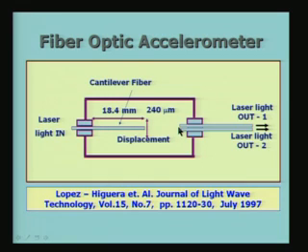At the downward side, I have got two optical fibers to collect the light which is coming from the left. These two fibers are kept with a small difference of spatially different positions, and you can see these are the two. So, what will happen is, if the laser beam is coming through this, a part of the laser light will enter through the 1 and the other part will enter through 2, and if it is symmetrically arranged with respect to this fiber, half will come here and half will come here, and therefore, the intensity of laser light coming through this and this will be exactly equal.